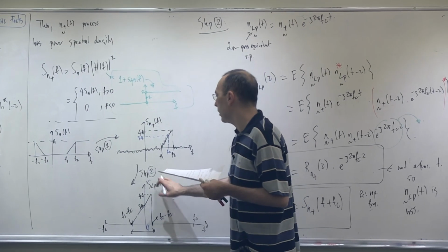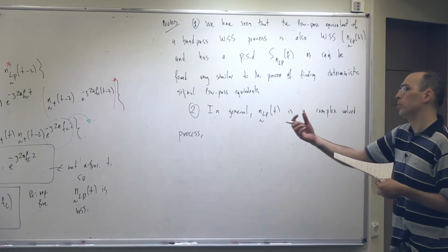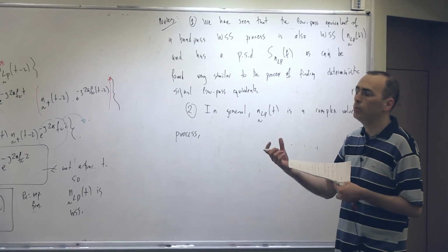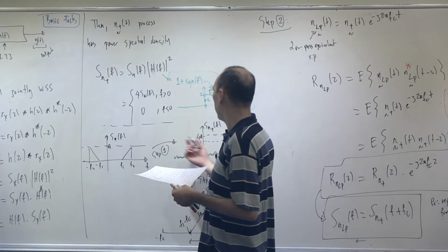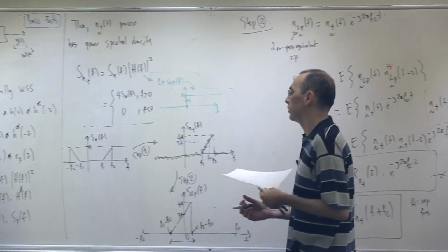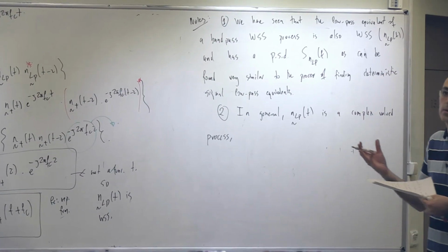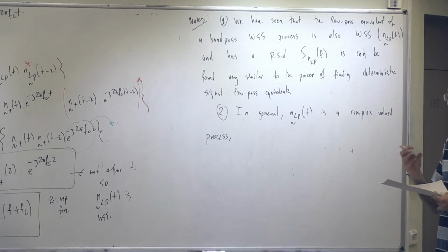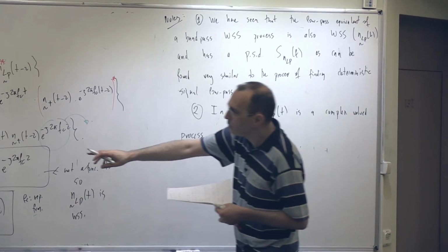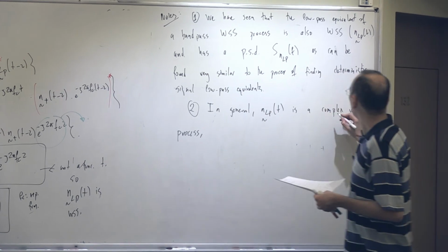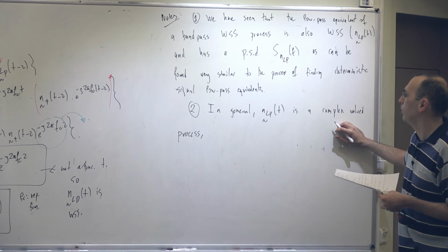So it's not called lowpass equivalent there, but I think lowpass equivalent is better because lowpass is something intuitive for electrical engineers, and equivalence is what we are seeking in many problems. Like in every problem, we are trying to find simpler and equivalent circuits, let's say. Or equivalent models of a mechanical system, things like that. So lowpass equivalence is a better name in my opinion, but in case you see it, it's also called complex envelope.